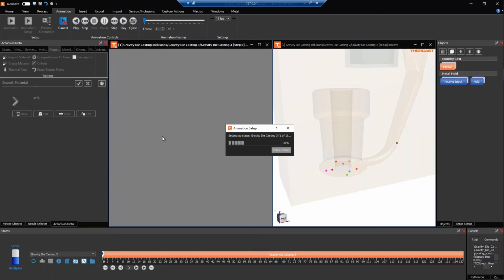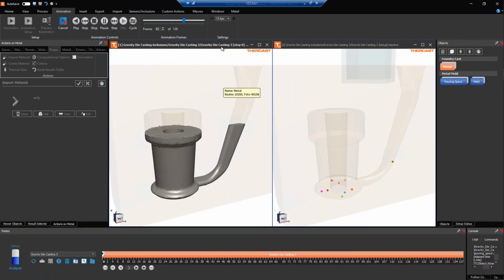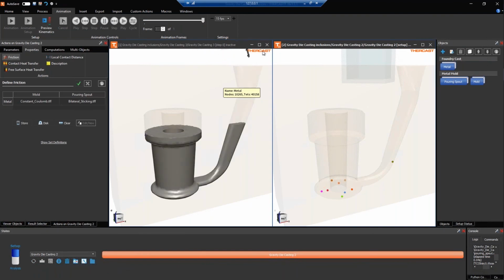you will see how the filling is proceeding during the casting time, and also how the inclusion will behave depending on their respective size and the competition with the local fluid. So okay, the animation is launched. You see that we have the filling from the melting pot here, and we have the solidification. This case is the one with the big, thick coating, and this one is with a smaller coating. So I will do exactly the same in this section.